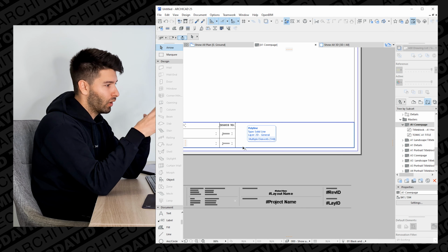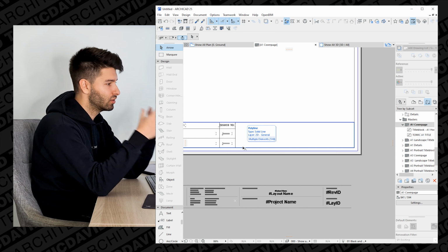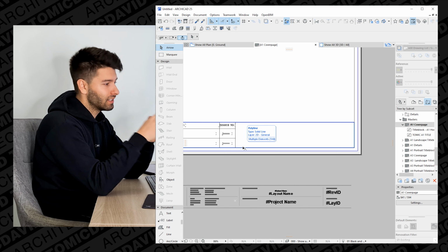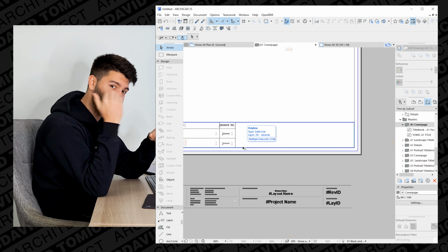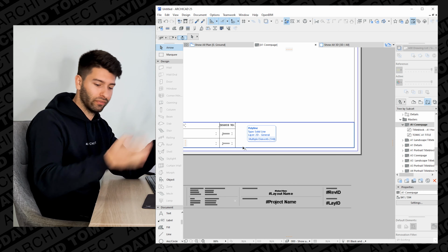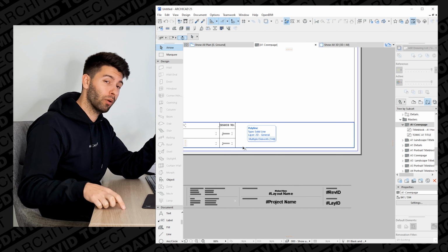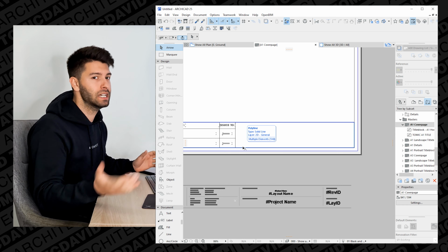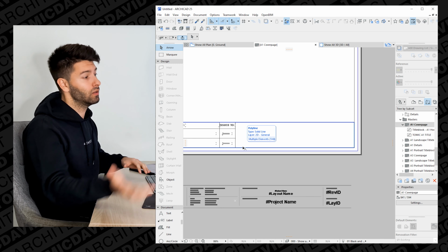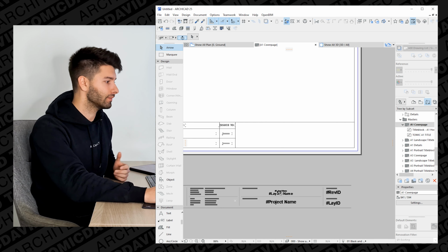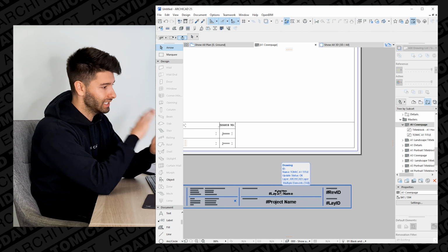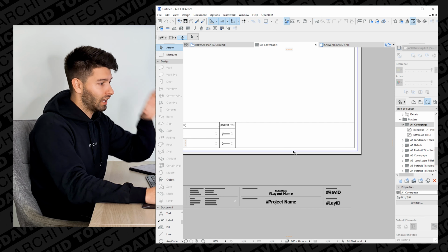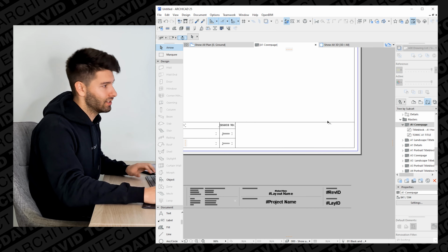Now this is the critical part of this title block, where all the information is stored about your project, about the job, about the page numbers, and basically where you reference. I personally like to leave it in the bottom right hand corner, because as you're flicking through pages, you're looking at that bottom right hand corner flicking over the page traditionally. You might be flicking the other way, but considering that most of the world is right-handed, we flick right to left. You can flip this entire title block around if you see that as different in your personal circumstances. But for me personally, I do like to keep all that information on the right-hand side of the screen.